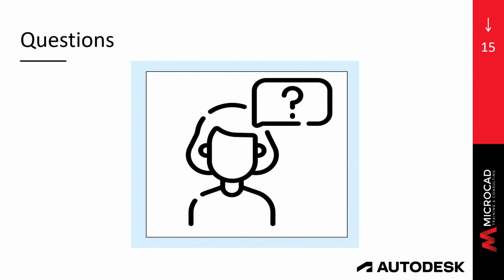Second question. How do you create a scaled 2D symbol for families? There are two ways. For example, the receptacle families have appended to them a nested family that is a generic annotation.